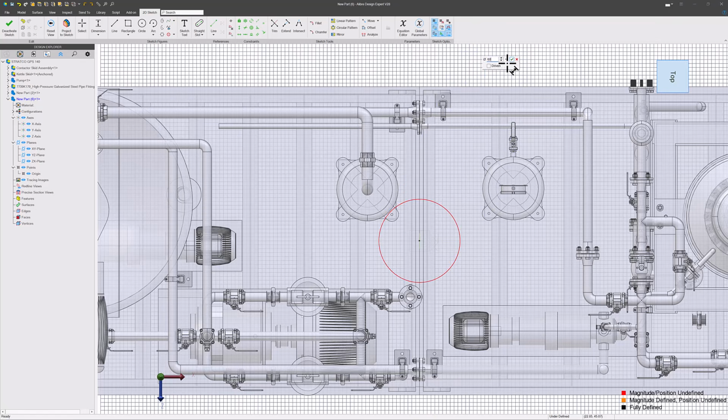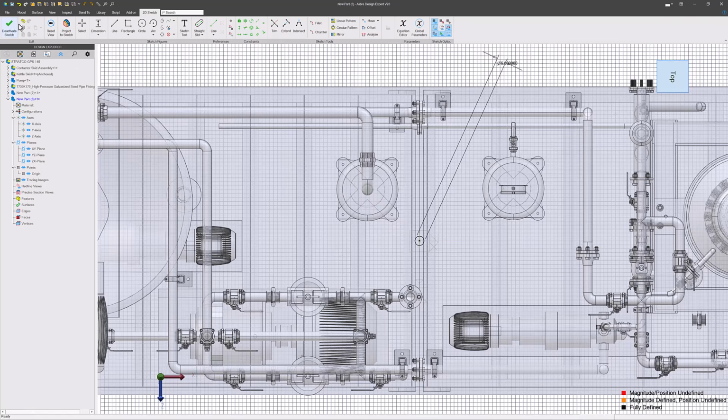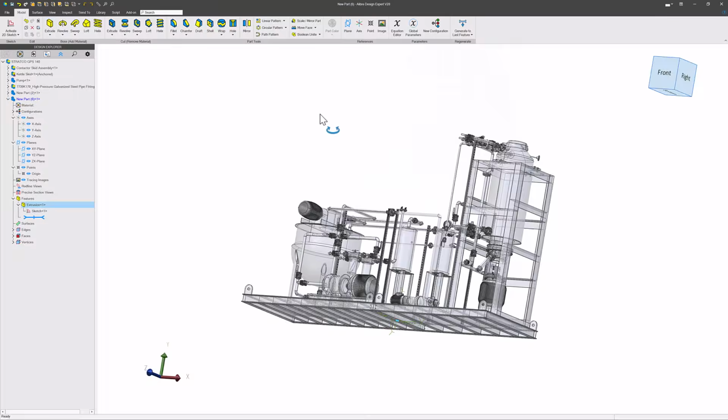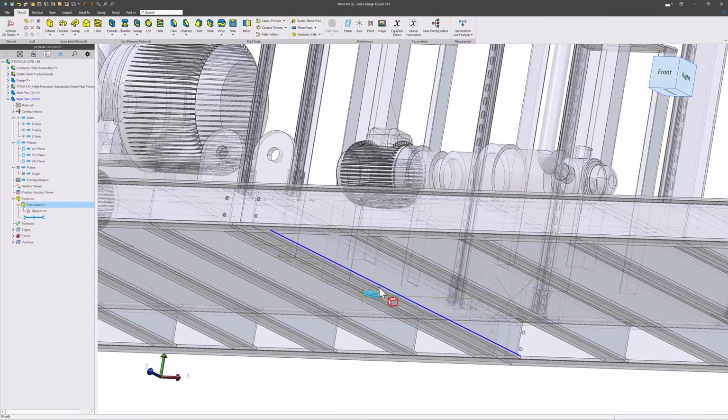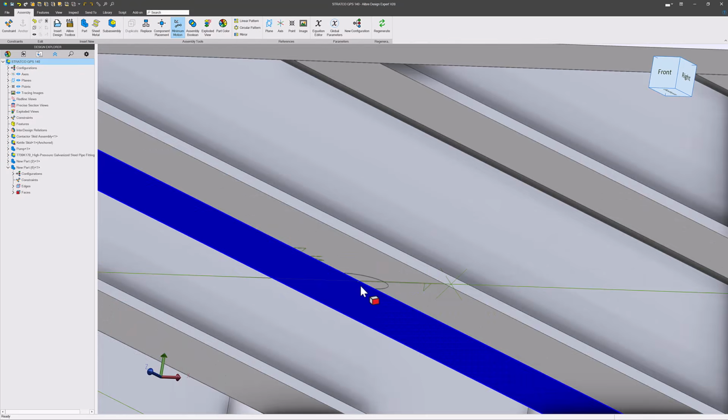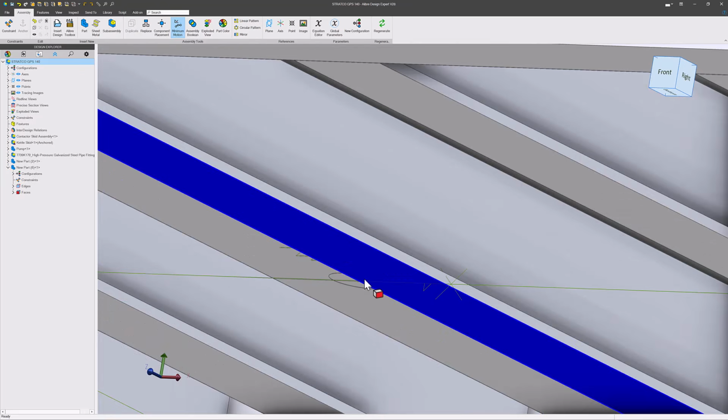I'm going to say 6.03 centimeters. And then we're going to give it a little bit of an extrusion, maybe 0.25, right? So this is still an independent part. We're not editing the part like with context references in this assembly or anything like that. And we'll go back to our main level, and I'm going to constrain this part now, right? And I can move it around. If I can get my mouse over it, I'll move it.